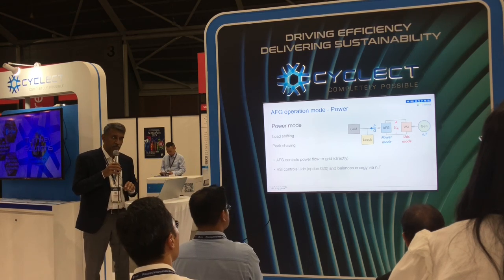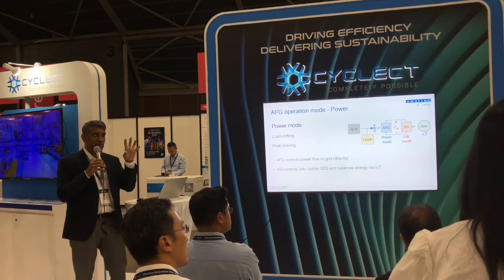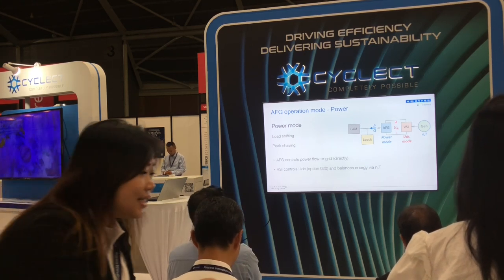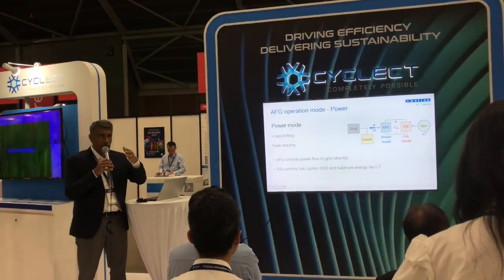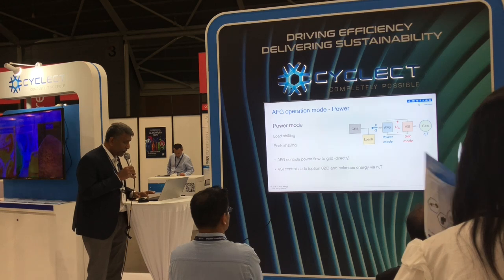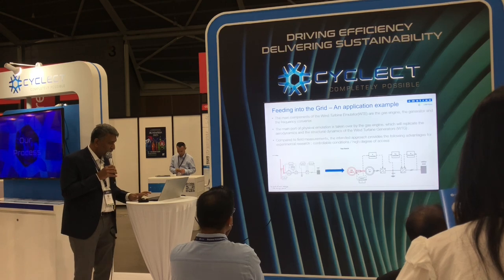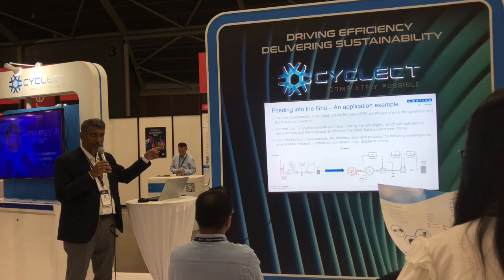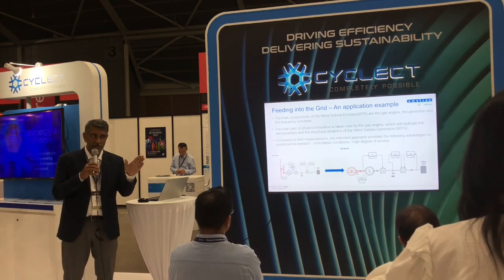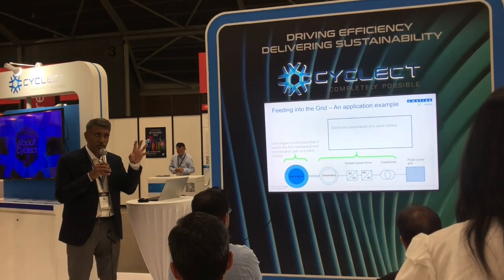But what we have done for a windmill manufacturer is something different. The windmill manufacturer wanted to study what happens to an electrical system when the windmill is operating. For example, if the windmill suddenly shuts down or the windmill speed is varying. But in this case, we went for a physical system called an emulator. So in the emulator, we have replaced the windmill itself with a gas engine. The other systems remain the same, but you can emulate how it works on a grid.